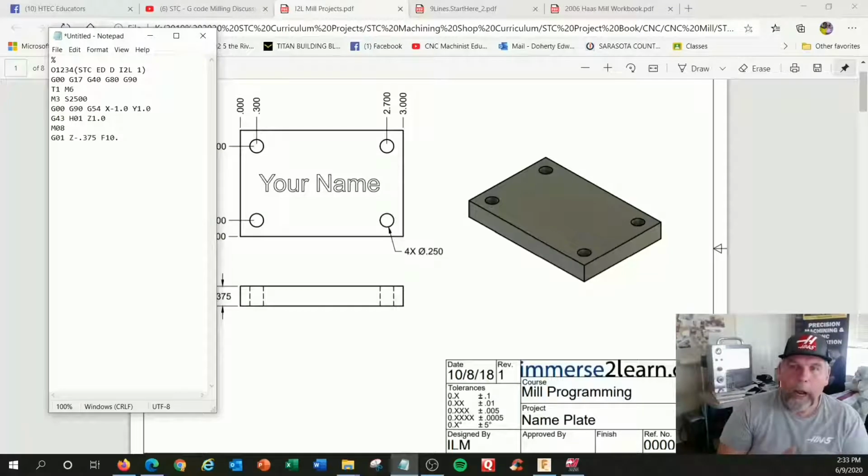All right. Now, this is going to be our go to Y0 compensation move, like I demonstrated. Okay. So it's going to be G41. We're still in G1 mode, so you don't have to type it. You can if you want. More typing, especially if you have to control like this. And you're going to say, which offset am I using? I'm using diameter offset 1. Okay. Where am I going? Y0. Or 0.0, they all work. And maybe I want that to be a faster feed rate. Maybe I want this one to be like 50. Speed things up, not cutting anything.